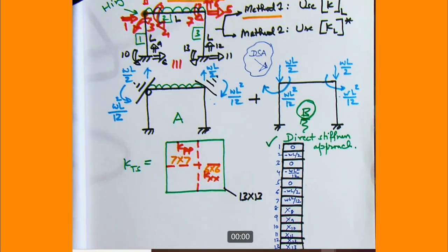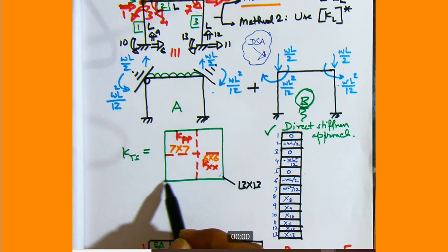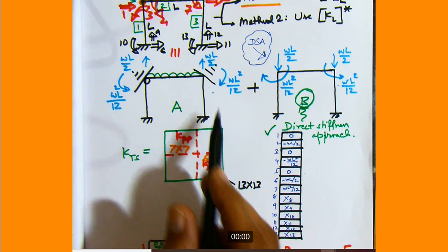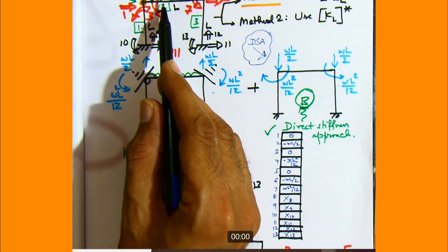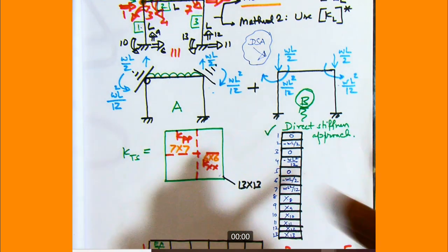Okay. And once we have done it, now we have to form KTS. Right now we just create KTS and initialize all values to 0. Now we have to form KTS. So how do we do it? One by one, in a recursion loop. Member number 1 will send all its elements, then member number 2 and then member number 3. So before that we have to form association matrices. So let's form association matrices of these members.